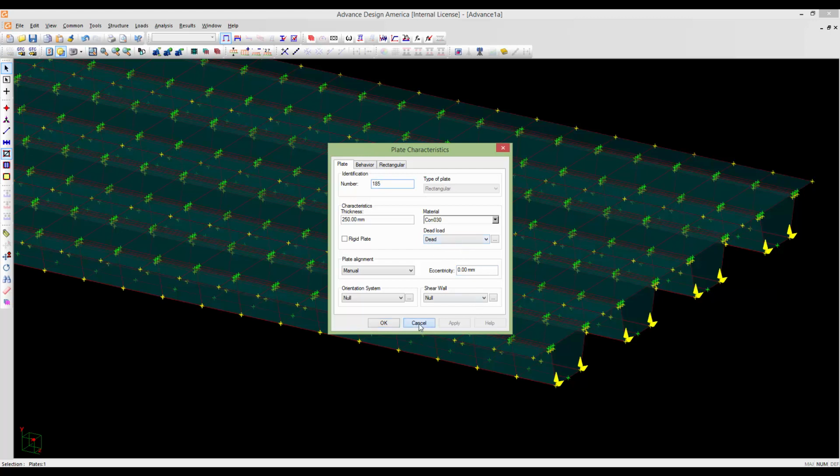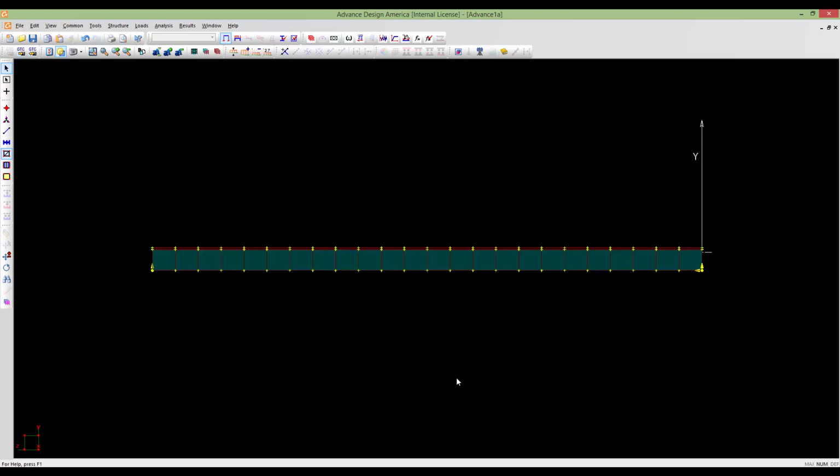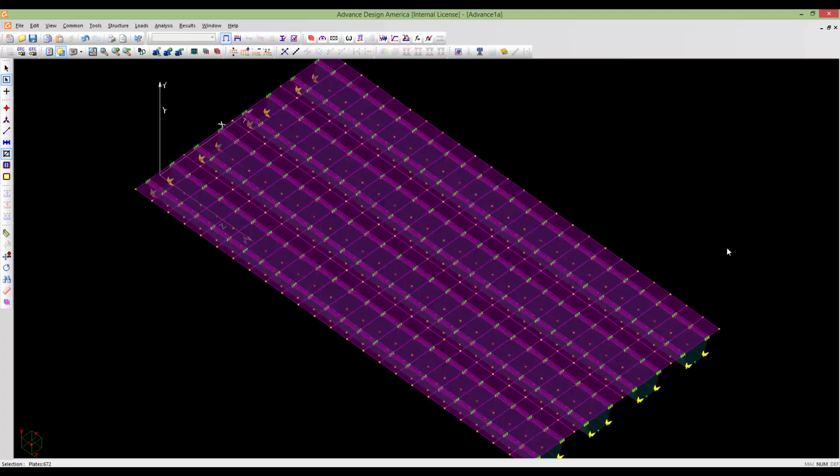So one thing that we need to do is you can always go to side view here, just select the concrete slabs with the restricted view, window, and activate the plates and just select these concrete slab.